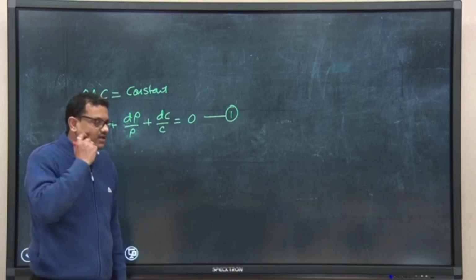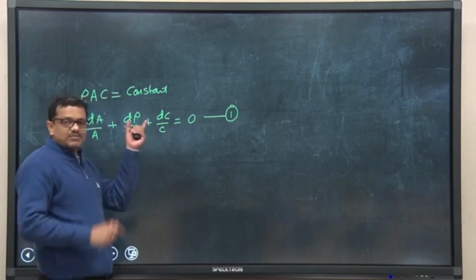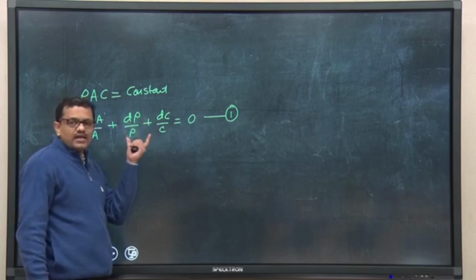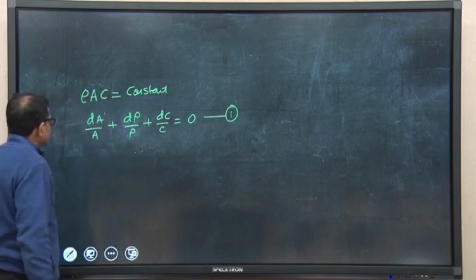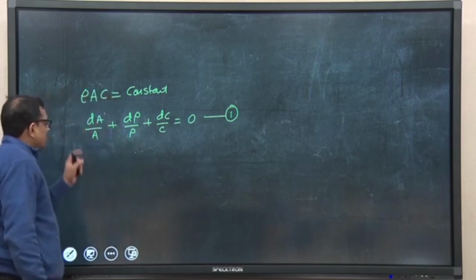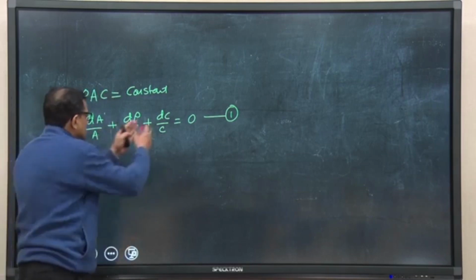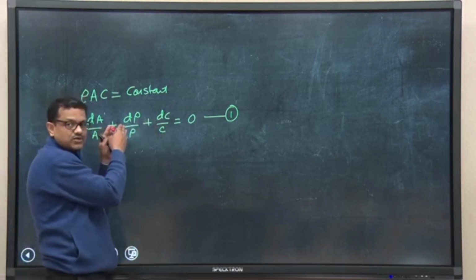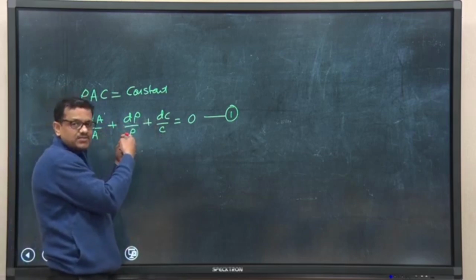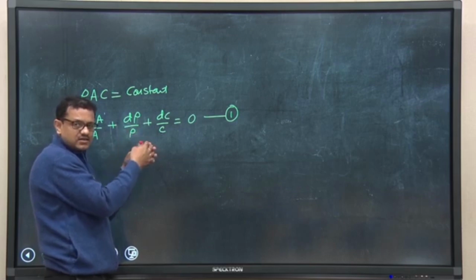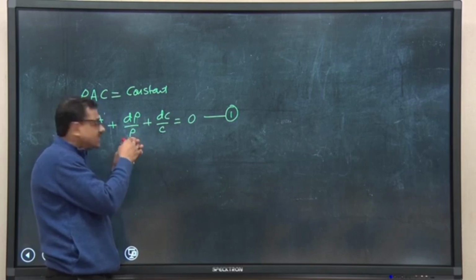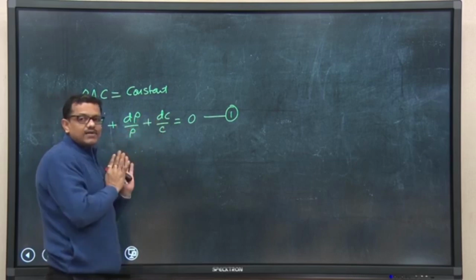The density will vary, and we have taken that effect into account while arriving at this equation. Our objective is to get velocity with area: what would be the area of the nozzle at its exit, knowing the area at its inlet, so that we can calculate velocity.